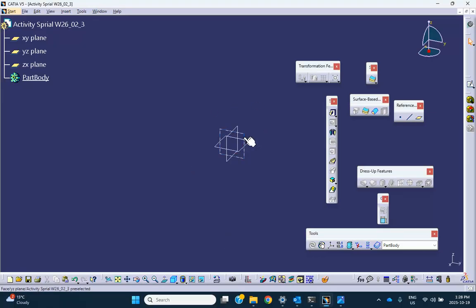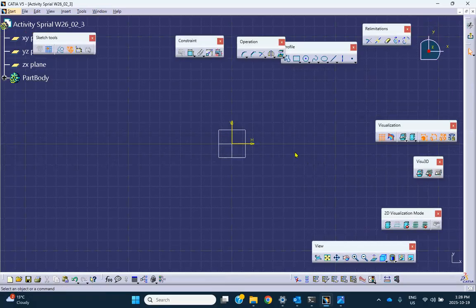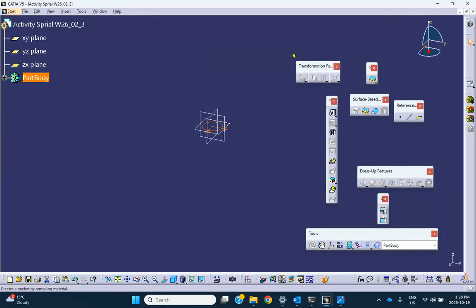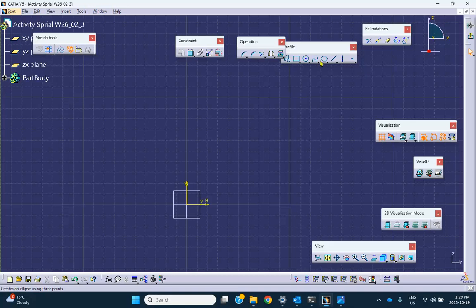So for example, on that horizontal plane, I will sketch a circle. This is the thing that I want to essentially rib or sweep along a different curve. So on that vertical plane, I will sketch a path, for example, like this.